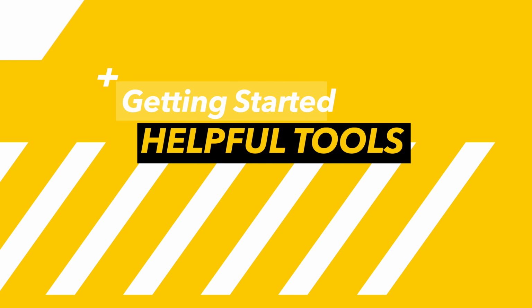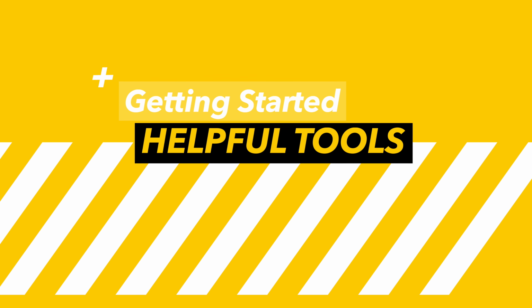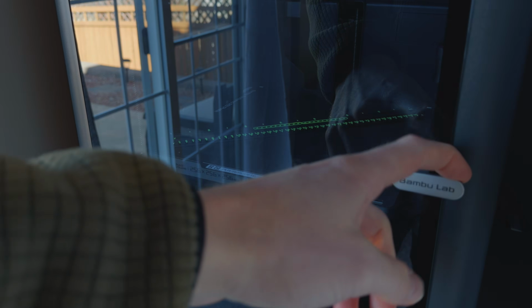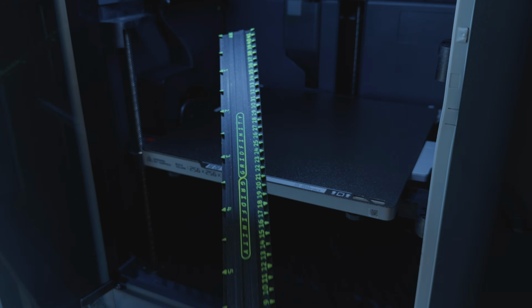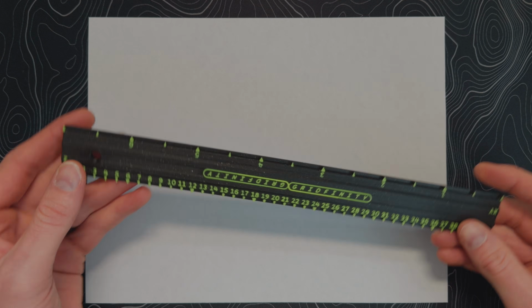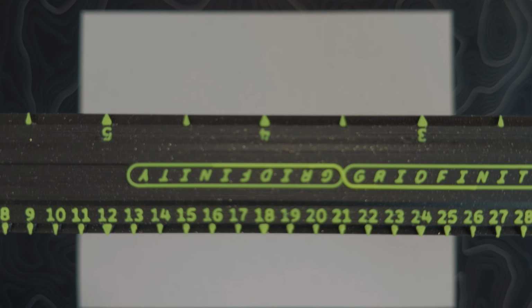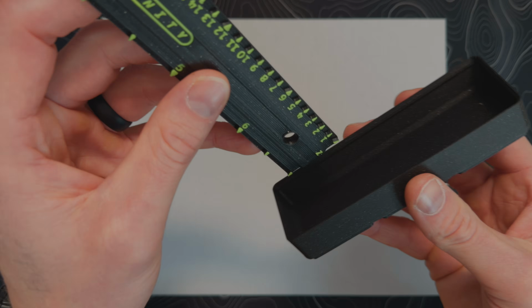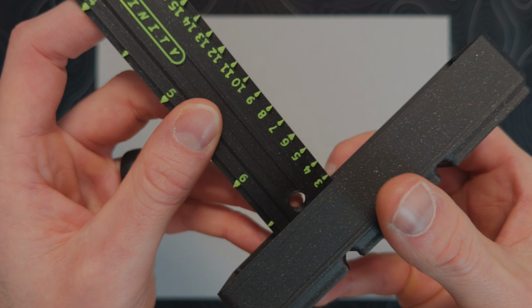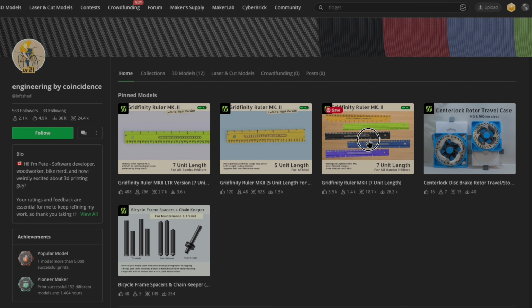Alright, so first things first, there are some tools you can use when designing your bin system that will be extremely helpful to tackle your setup. Assuming you have access to a 3D printer to make your bins, you can download and print a Gridfinity ruler. The ruler is set to the same 7mm base units and the 42mm grid spacing that match the standard bin system, and it makes for a quick and easy way to measure your parts and even your existing bins to figure out your sizing. I highly recommend this one I found that's designed by Engineering by Coincidence on MakerWorld,